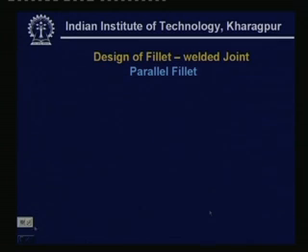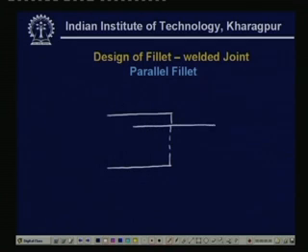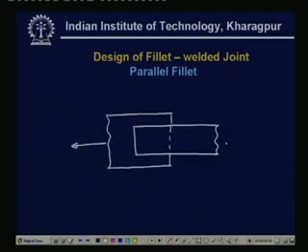Now, we consider the parallel fillet. Here it carries a load P. Parallel fillet is the fillet which is applied here, that is, the welding is done in these two places. This is longitudinal fillet or parallel fillet.